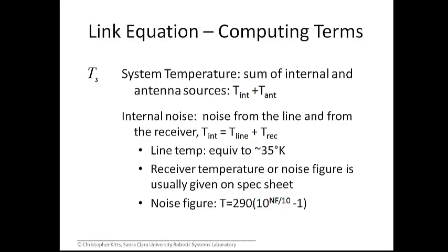But it's a very broad spectrum emission that you get from black body radiation, and part of that radiation comes off in the microwave range. So anything with a temperature is emitting radio waves. Now, it may be a very small amount, a very low amplitude, low energy kind of wave, but it's radiating across the spectrum. So the portion of that near the range in which we're receiving, we're going to pick up some of that, and that's not the signal we're looking for. So that's a source of noise.